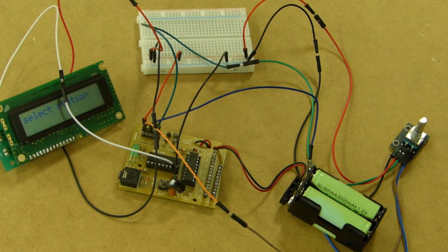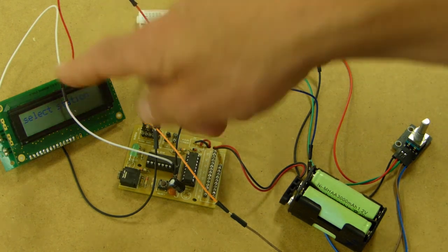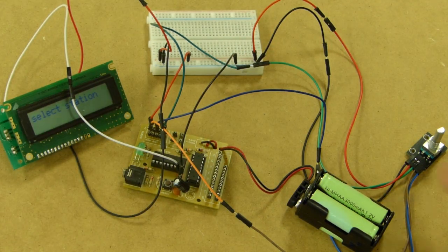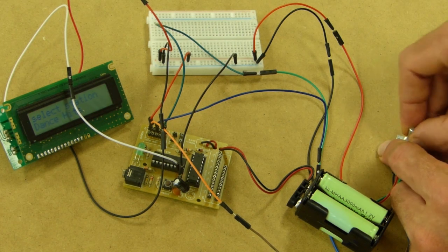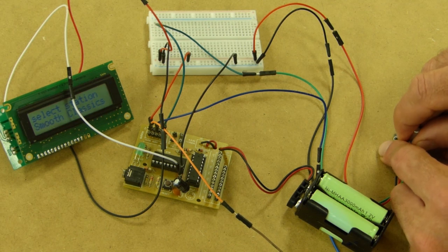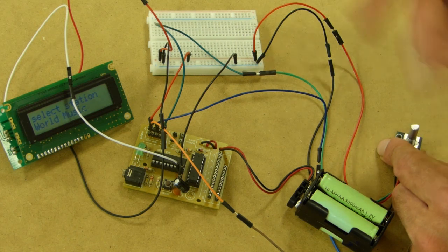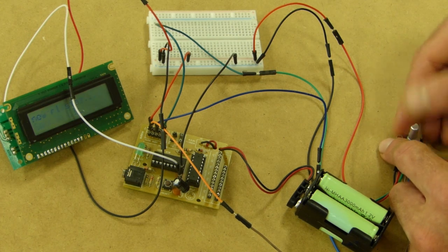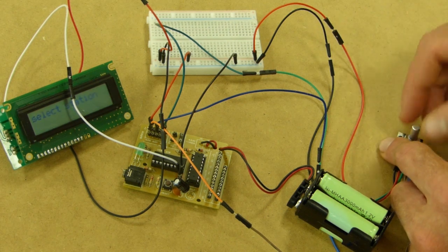Okay, here's the circuit in real life, having uploaded it onto the Genie. As usual, we're just using a breadboard to share the plus volts and the ground with the LCD and the rotary encoder. You can see here I'm in the beginning state on the LCD, and then as soon as I move this, I start adding data values. That's going to be 1, 2, 3, and then if it's 4, it goes back to 1. If it goes down below 1, like 0 or 255, it will go on to 3, as with the flowchart. And then when I push the button, it goes into the other state, so it just says what it's playing. And then push it again to get out of it. And that's it.